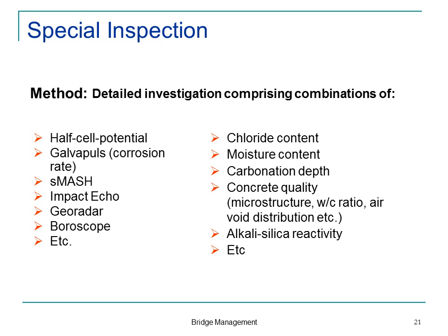Okay. What methods do we use in the special inspections? I would say any method that works and isn't too complicated. At least it's some that we use for the concrete structures. We focus a lot on water ingress, chloride ingress. Chloride is a part of the salt that causes corrosion.